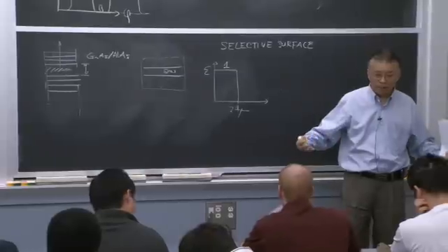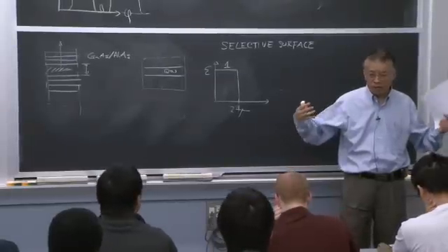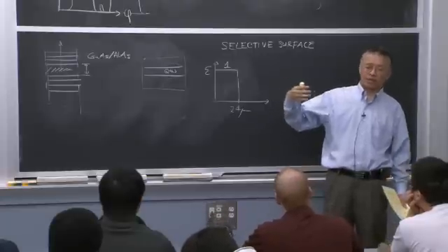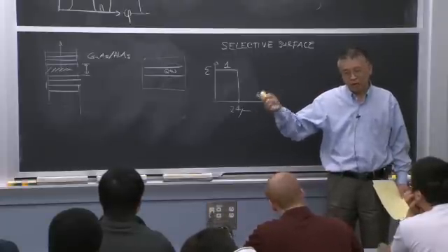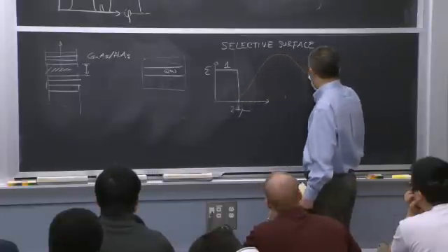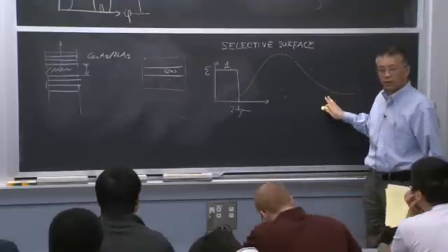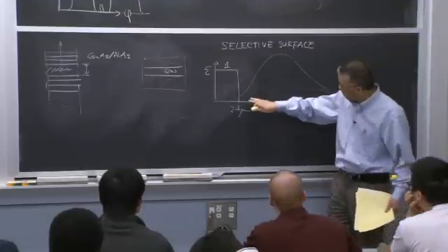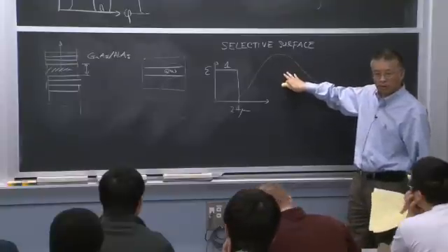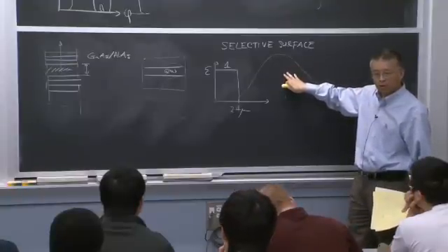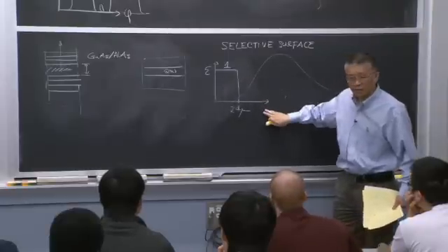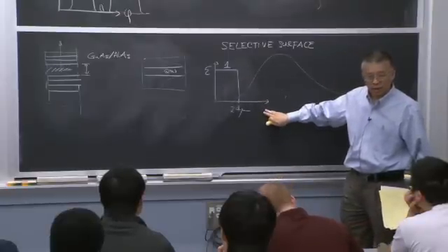When you heat up an object, you think about Wien's law, right? Lambda T is about 3,000. So if your object is 500 Kelvin, your wavelength is about 10 micron. That's the peak wavelength, so the black body emission from the surface is here. If you can minimize your emissivity to 0, you don't lose as much heat, right? So that's what the selective surface does. Ideally, I want the emissivity to be 1 and 0 here.